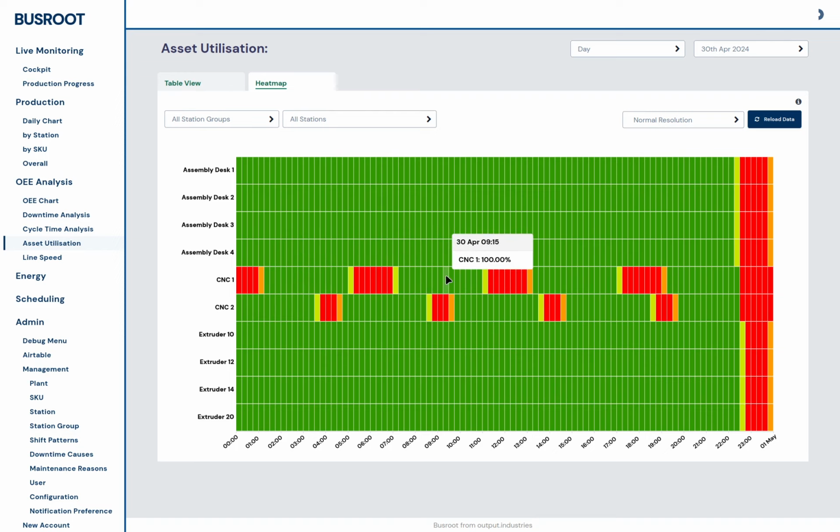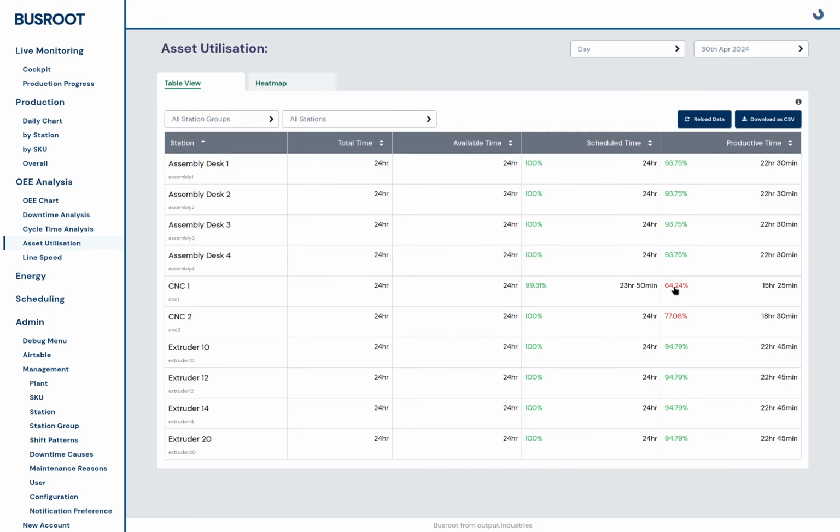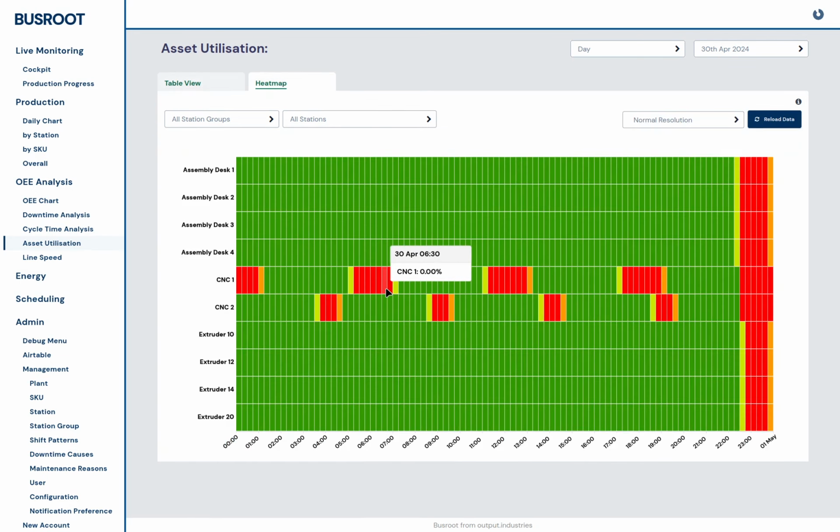So you can visualize now the changeover times of the machine, and you can see this line here on CNC1, this might represent a completely normal operation. The CNC machine is running, then it stops, then there is some kind of unloading and loading process, then the machine runs again. So it's typical for this CNC machine, for example, to reach a productive percentage of 65%, just because of the amount of time that's spent loading and unloading the machine, where it's not actually running and adding value. So I hope you can see the different ways that this can be used to analyze the actual manufacturing process, and maybe look to optimize some of those things, and understand the actual utilization that's being done on a lot of these assets.